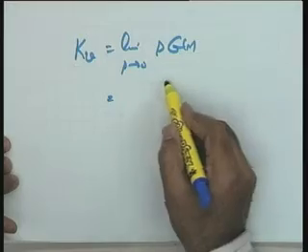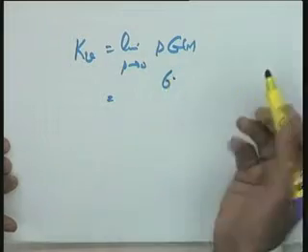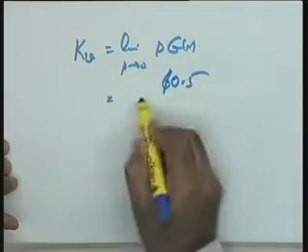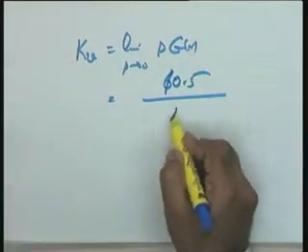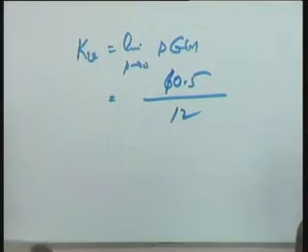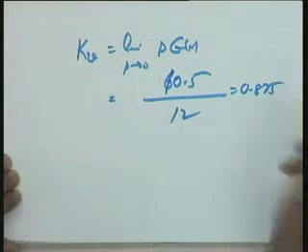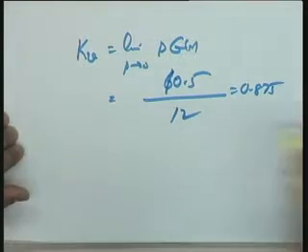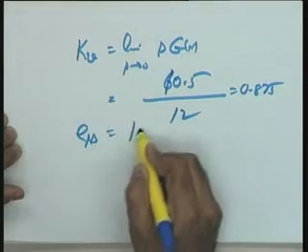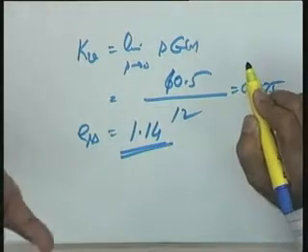Okay? So, correspondingly Ka value can be calculated. It will be 10.5 divided by 60. But let me calculate the Kv value. So, the Kv value is going to be 60 into Ka, which is 10.5 divided by, yes, help me please, 12. Is it all right? Yes, it will be 12, that is fine. 10.5 divided by 12, which is equal to 0.875. You find that the Kv value is too low, and the steady state error in this particular case is going to be 1.14 radians.